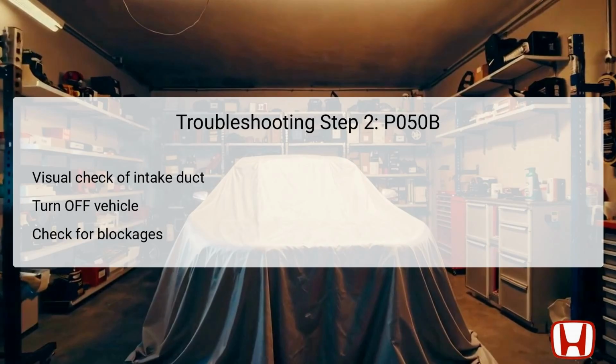If you identify any issues such as cracks, loose fittings, or significant blockages, these must be addressed immediately by either reconnecting or repairing the duct. If the duct is severely damaged, replacement may be necessary to ensure optimal airflow, allowing the engine to function correctly during cold starts.